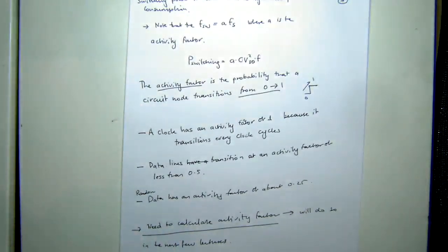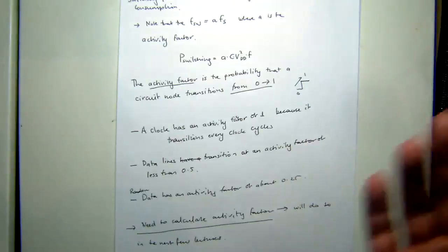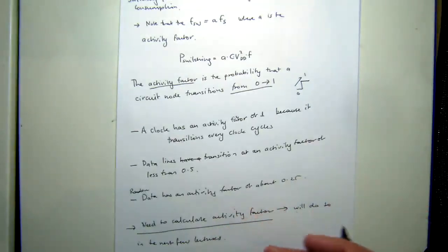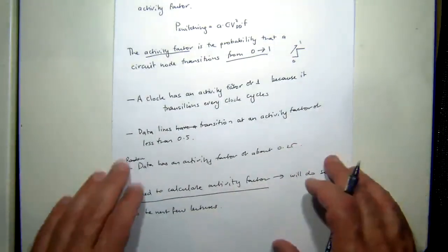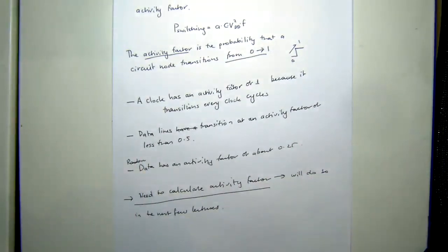Okay. And we've just described this, and your colleague has just pointed out that a clock has an activity factor of 1, but not all other components or elements or gates have the same activity factor. I can almost guarantee you that they're probably closer to half, except for clock buffers and things like that, because not everything's constantly transitioning with the clock.